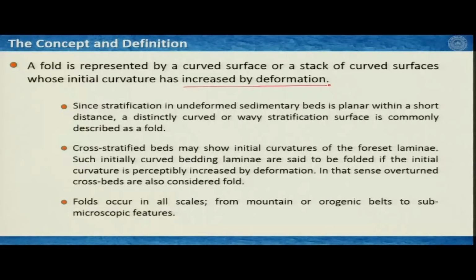The cross stratifications, as you know, this is a structure like this. So, you have sedimentary layers, and in between you may have a very typical sedimentary structure like this, and this has a lot of information. First of all, it tells you the younging direction of the sedimentary deposit. It also tells you the flow direction, paleo flow direction, and so on. Now, essentially we see within these two layers this sandwiched structure. Now, there is some sort of curvature, as you can see in this illustration.